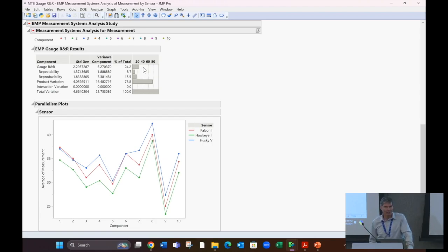So then you kind of take a step back and say, well, wait a minute, how would I do that in my test? I'm already up against the wall trying to ask for 15 runs, and now you're telling me I need 3 for each one. And so in many cases, this is a function of folks in the lab, so to speak, to make sure that their instruments are tuned properly. Gauge R&R.